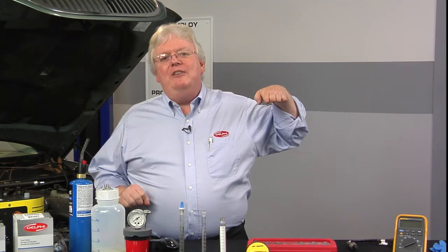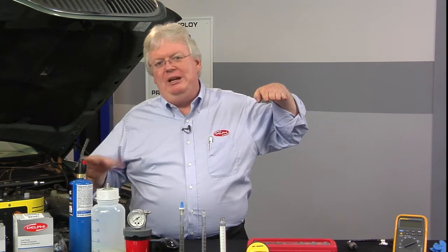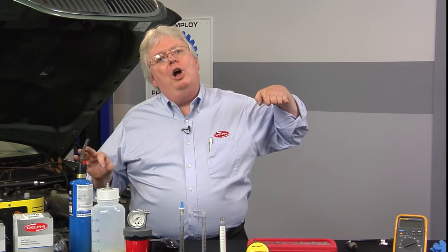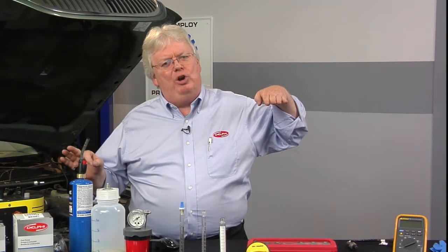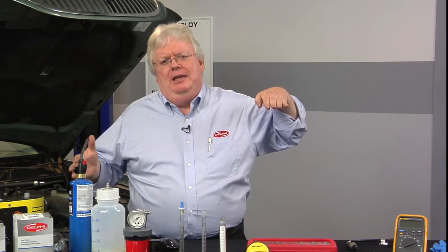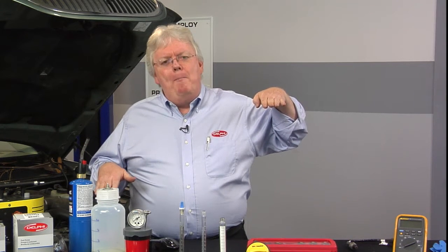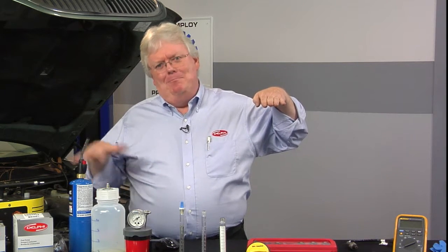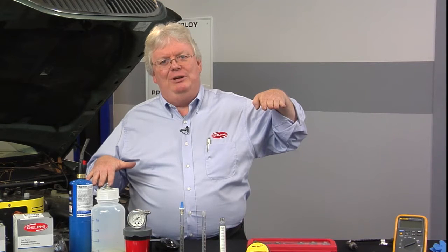Think the opposite with these air fuel and wideband sensors, either measuring in a voltage between 2.5 and 3.5 volts or so, or a very small current, 20 milliamps typically, of movement. The number of milliamps, positive or negative, will go with the air fuel ratio.